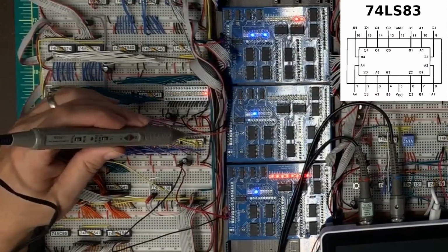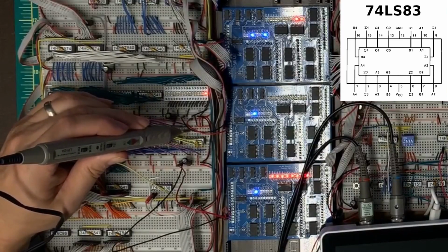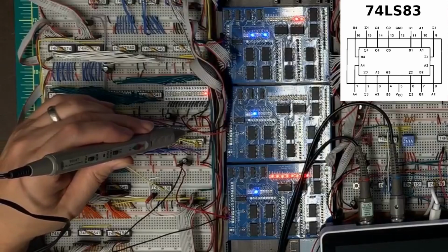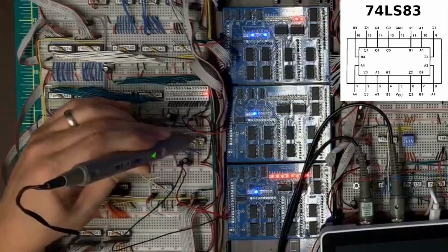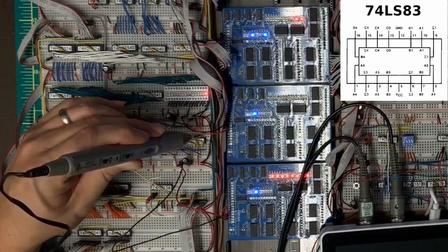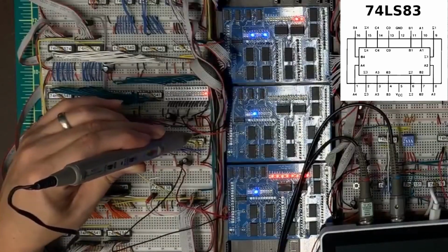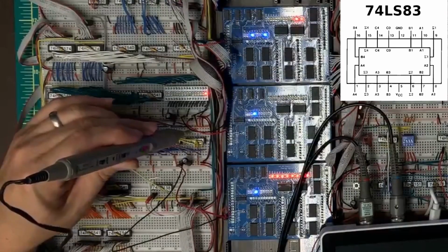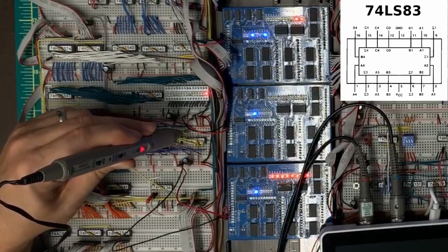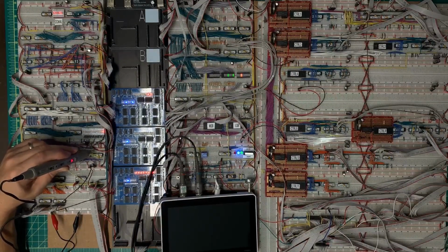I've got inputs A up on the top here, inputs for 1 up on the top here. Okay, so that's correct. So that is sum 1, which is low, high and low should equal 1 unless carry 0 is coming in high, and it is coming in high. So that then is what is driving that.